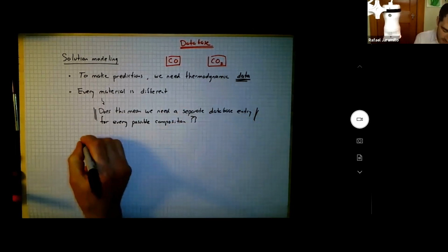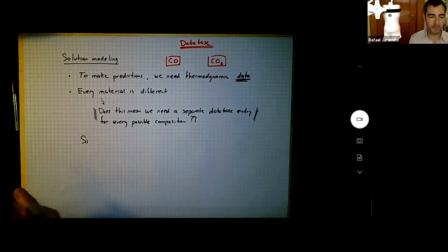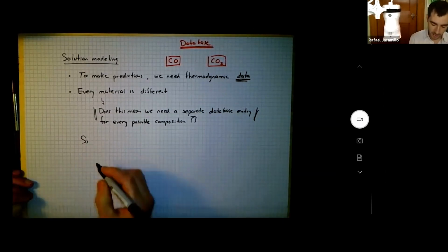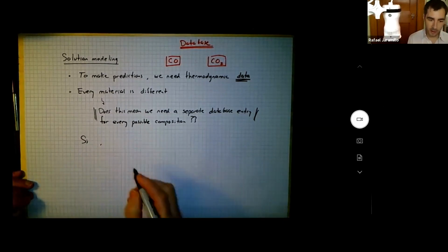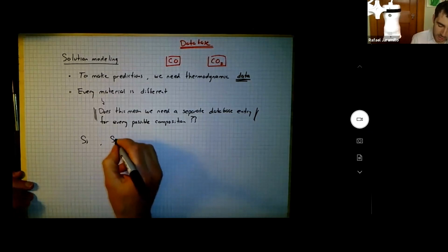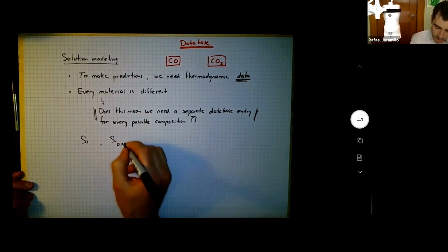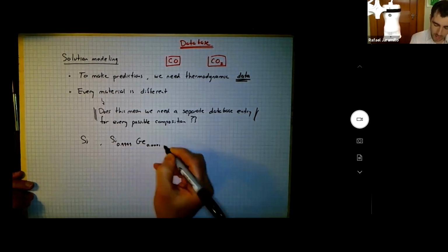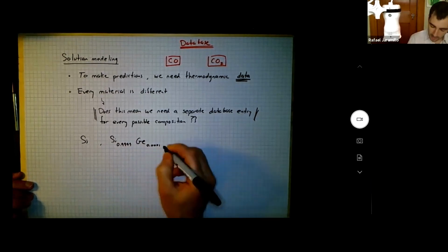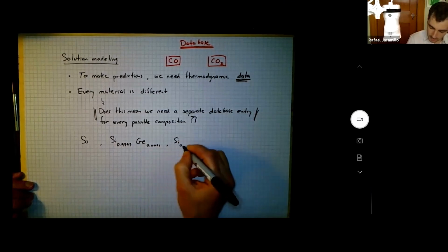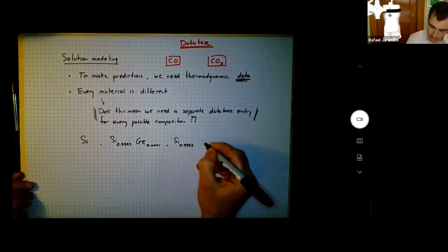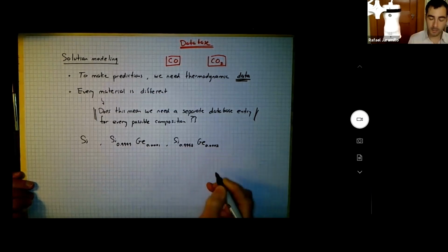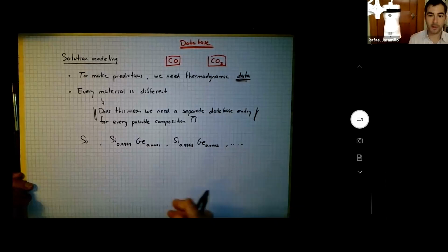Let's say we have silicon, and let's say like Professor Fitzgerald did when he developed strained silicon, which is now in every transistor below the 40 nanometer node, he started alloying it with germanium. And he added a little more germanium. And maybe add a little more.